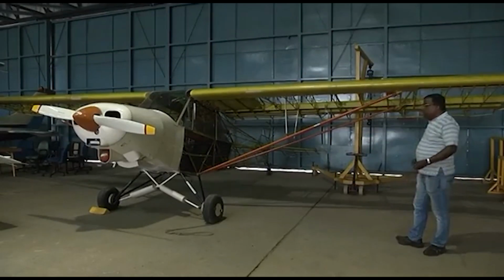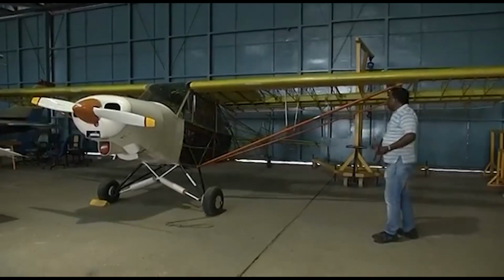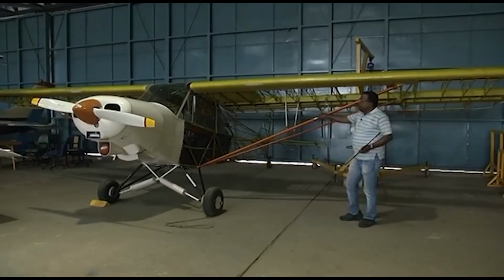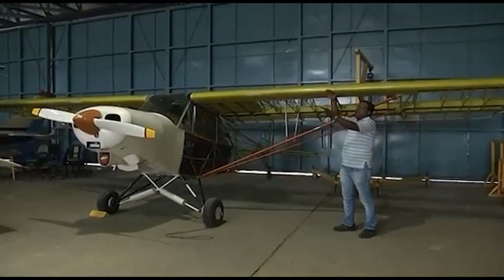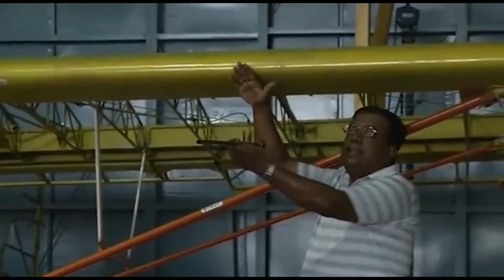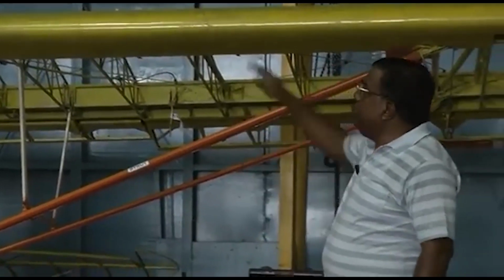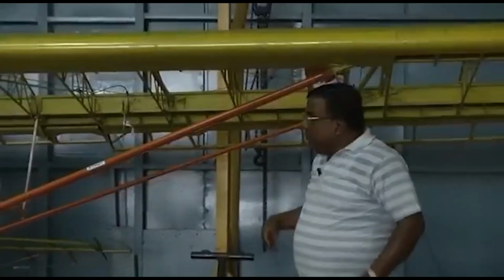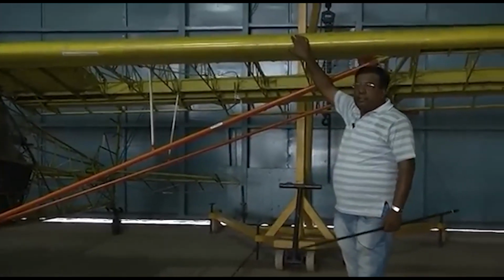Okay? What is the difference between this configuration and the tricycle configuration? You could see even in this position, this wing is making an angle of attack with the velocity vector. If it is going straight, there is the angle of attack. So when we are going for a takeoff, it already has a high angle of attack, but the moment I start the engine and try to do taxiing, this will produce a lot of drag. Okay?